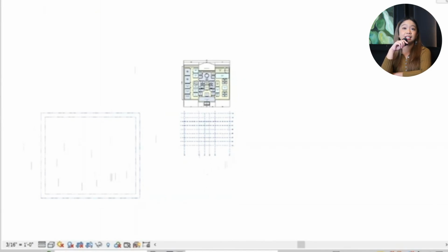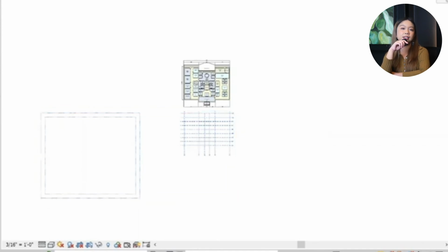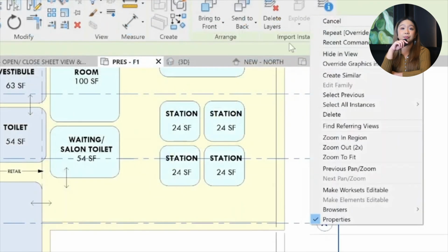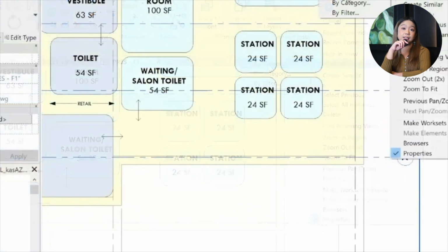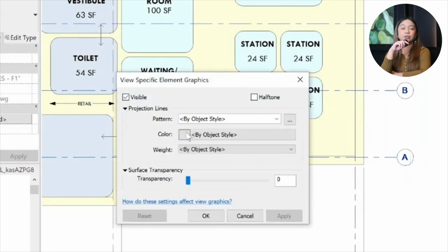To align the CAD file, I place it by matching the intersection of grid lines to where I want the grid in Revit. While you could use the CAD file as an underlay, I recommend creating Revit grid lines instead. Revit grid lines are intelligent. They appear in sections, elevations, and floor plans, making them far more versatile than CAD underlays. Use the Architecture tab and select Grid to trace over the CAD lines, creating your own Revit grid system. You can copy these grid lines across modules using constraints for precision.